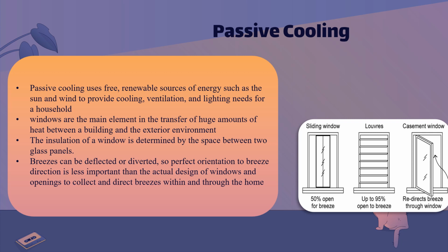Wind does not actually blow through the building. It is sucked to the area of lower pressure. To draw the breeze through the house, use a larger opening area on the low pressure side of the house and a smaller opening area on the high pressure side. Openings near the center of the high pressure zone are more effective than openings on the edge, because pressure is highest near the center of the wind wall and diminishes toward the edge as the wind finds other ways to move around the building.